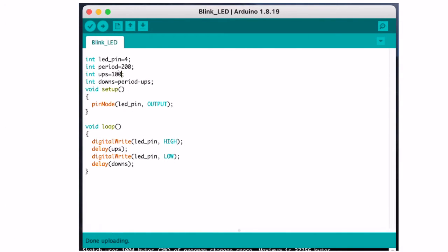Okay, let's quickly look at the coding part needed for blinking an LED. We are using pin number 4. Programming here is essentially in C style. Those who know C can easily do it. Otherwise, let's go through it. The basic structure of a program consists of a setup, which is the initialization of code. Necessary variables and pin configurations are set up here. Then we have a loop which continuously runs without ending. Here is the main code which runs continuously in the loop till you switch off the system.